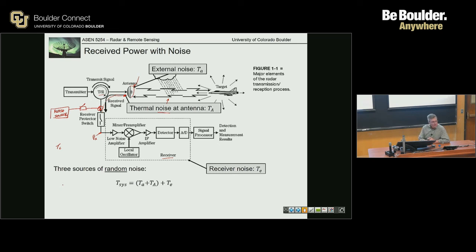More like there are components where at a higher temperature the noise floor would be higher, but it's not amplifying any noise. If I have two coaxial cables connected together with a 50 ohm load at the end of one, and I measure the noise power coming in, and then I take one of those cables off and put the 50 ohm load at the shorter cable, my understanding is I would get the same noise power coming in.